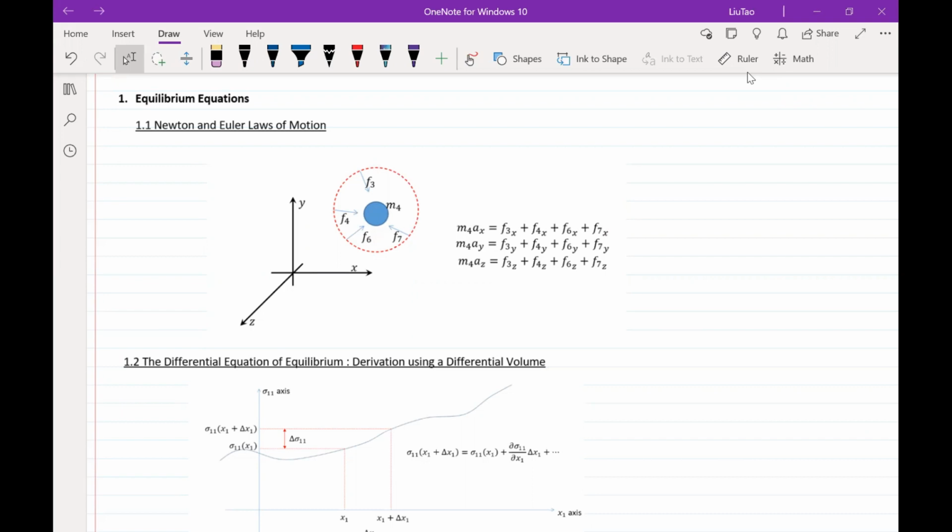The extension of these equations to a continuum allows the study of the deformation of objects by studying the motion of the relative particles on a continuum with respect to each other. When we are studying the mechanics of a continuum, we are usually interested in the deformation of that continuum after applying external forces onto the object. Euler basically stated that you can treat any part of the continuum as a particle and apply Newton's law of equation onto that particle.